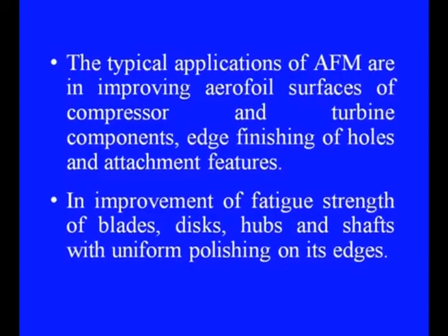Now, let us see a few typical applications of this process. As I said, the process was initially developed for effective deburring of hydraulic control blocks. However, later on the field of application of this process rapidly diversified into defense, medical and other manufacturing units. The typical applications of AFM are in improving aerofoil surfaces of compressor and turbine components, edge finishing of holes and attachment features,